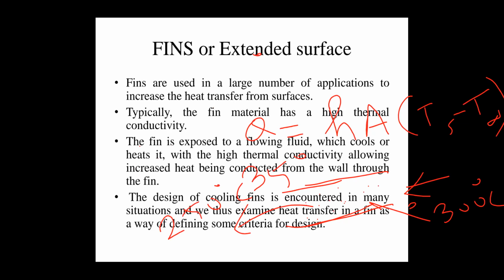So a 300 degree fluid exits at 250 degrees Celsius because of the 35 degrees Celsius atmospheric temperature. To increase the heat transfer rate, it is possible to increase the convective heat transfer coefficient.